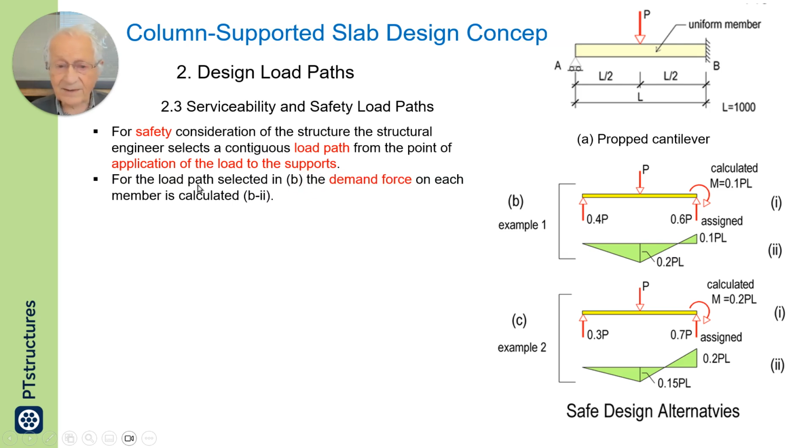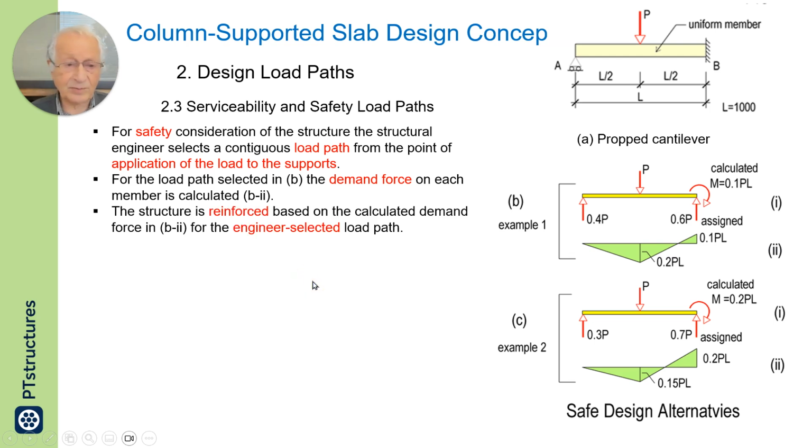The load path selector gives the demand force for each member. Based on the load path you select, you calculate the demand. The demand in B is different from the demand in C, but each demand satisfies the selected load path.